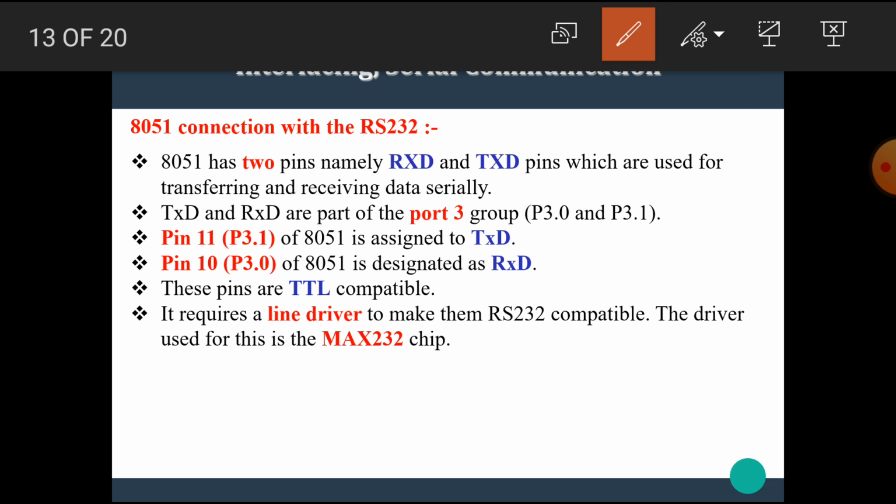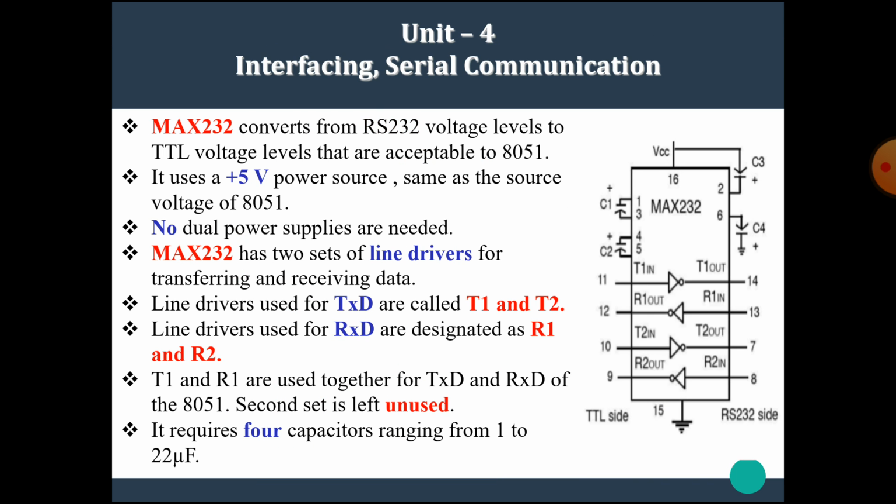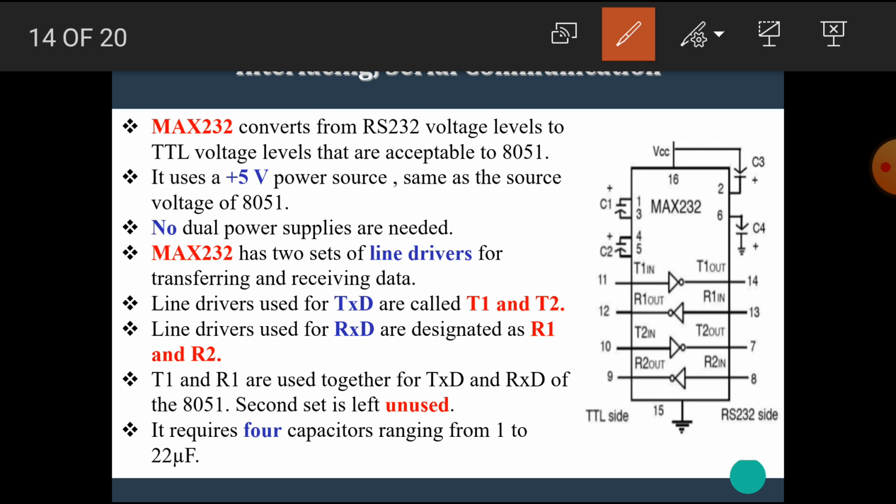That means here the TxD and RxD, these two pins are TTL compatible. To make it compatible with RS-232, we use a line driver chip named MAX232.